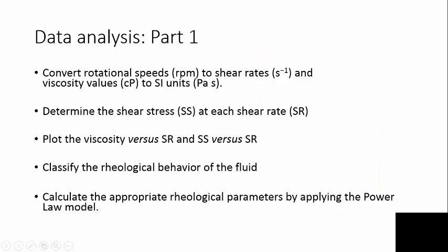So once you collect all that viscosity data, which will be the speed of the spindle and the viscosity value in centipoise, then you'll need to do some conversions, find shear stress, plot viscosity and shear stress, so that you can then classify the rheological behavior of the fluid.